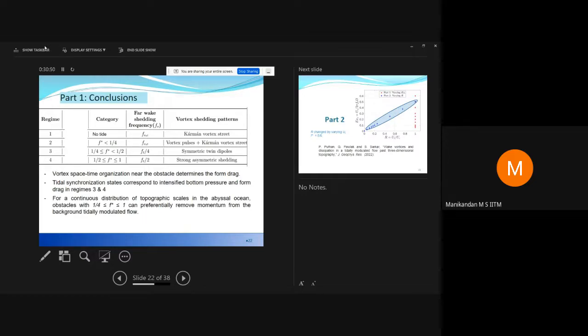So this is a fully three-dimensional vortex field. If you saw the pictures, you saw these vortices, right? But the size of the vortices changed, while the frequency did not change. So it's a global frequency based on the base diameter. It's one frequency.